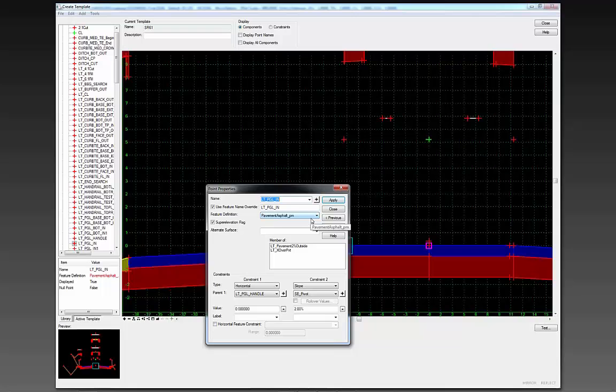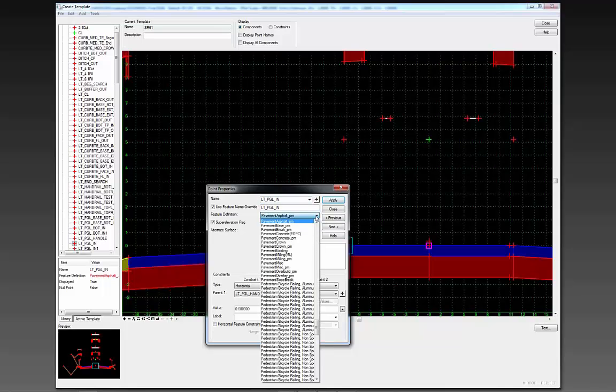And that's why we make sure that if you're creating your own, you don't select any of the 2D features, because the 2Ds and the 3Ds get mixed up in this list. Unfortunately, in this template point properties dialog, it doesn't give you the ability to look in by folder, whereas when you're drawing features, you can select folders. I'll go do that in a second too. But you want to make sure you're using PMs for points.